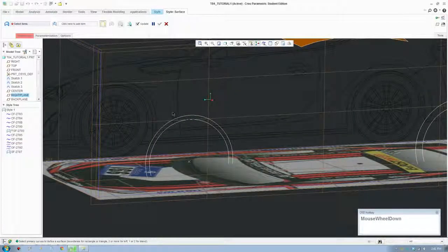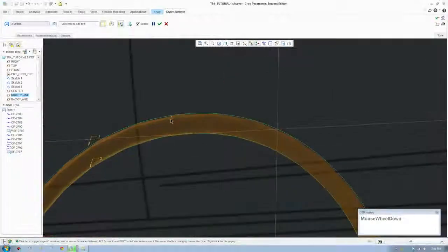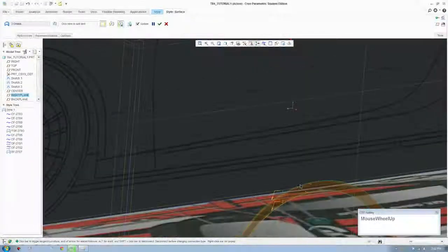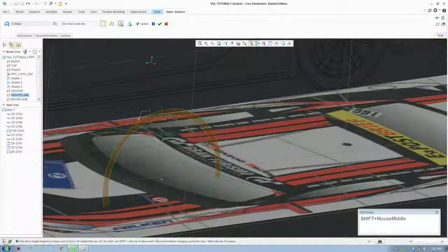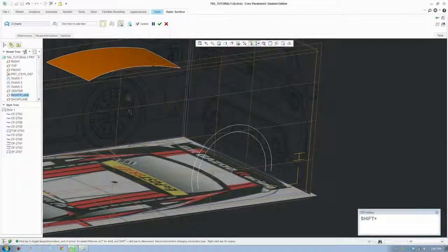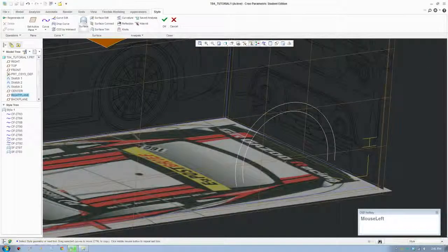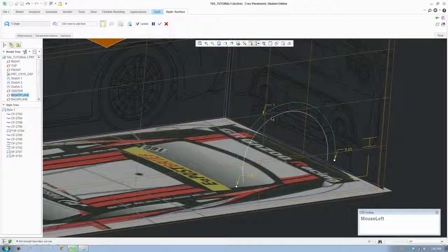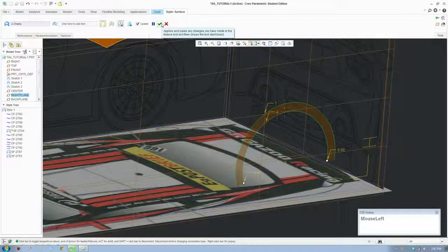It's a flat surface on the fender, so be careful, there are these little arrows here that tell you the tangencies. We have to change that to position so it doesn't force the form to have a normal tangency. Now it's flat, and we're going to do the same for the back. Change that to position. What normal means is it's just normal with the curves.